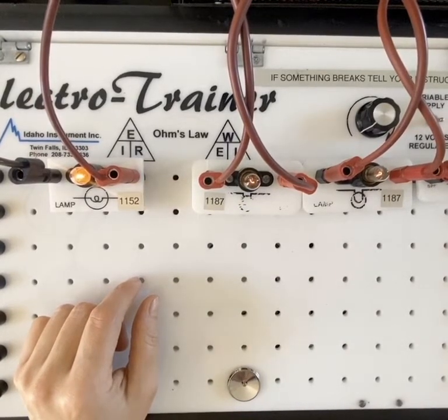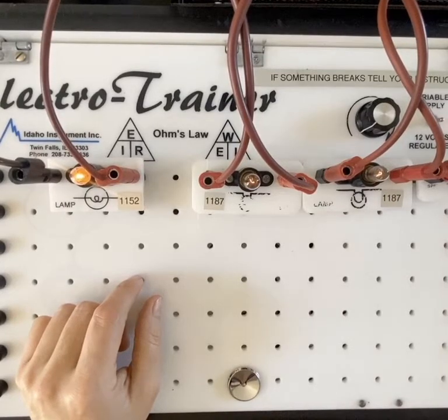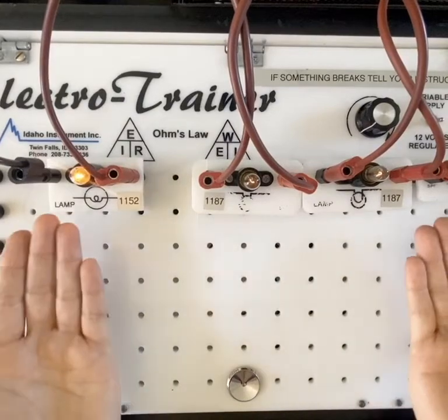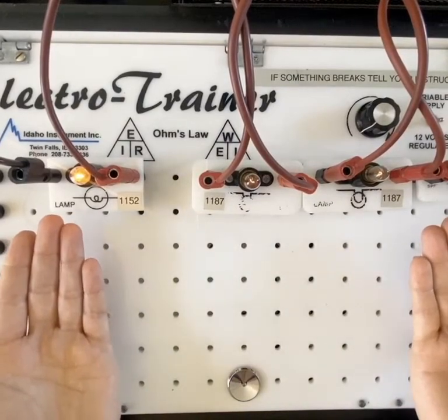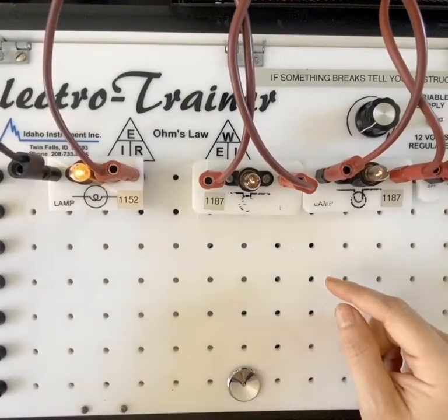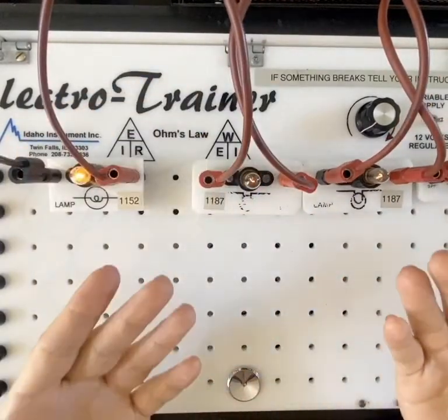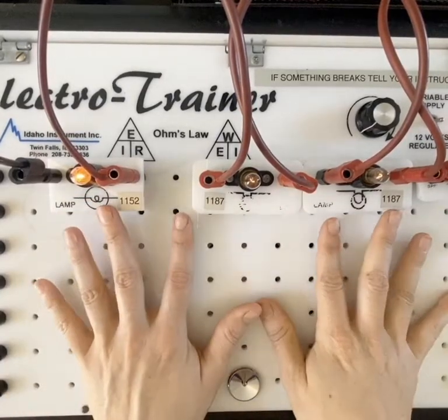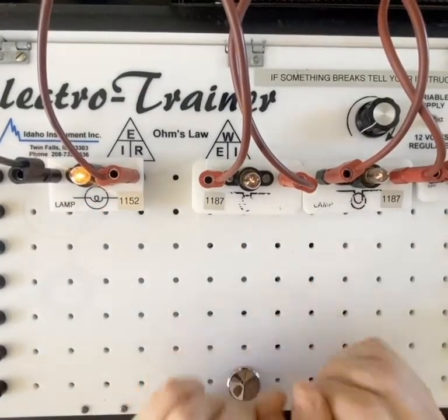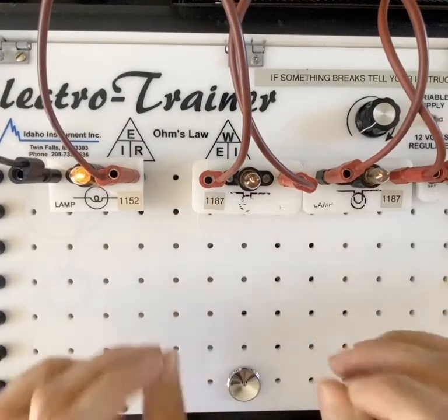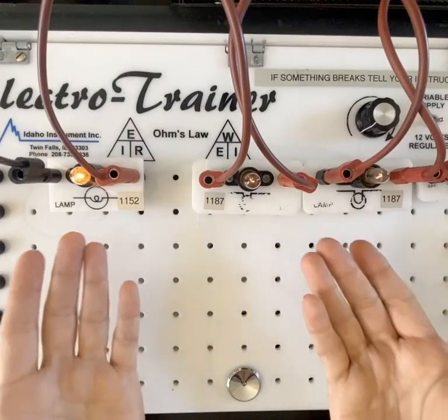Now, sometimes the logic behind that is, well, more resistance, less amperage, right? Yes, but this is a series circuit. So we need to remember that we have the same amount of amperage here as we do down here, as we do here. So it's definitely not an amperage difference because they're all getting the same amount of current flow. So what must be different? Well, we do know that ohms are different. They've got to be, right? Something has to be different.